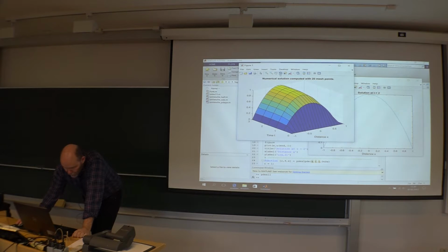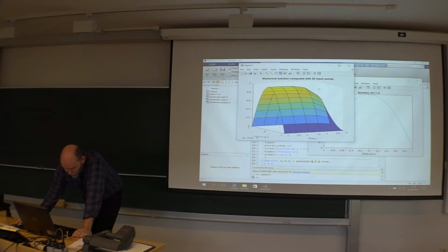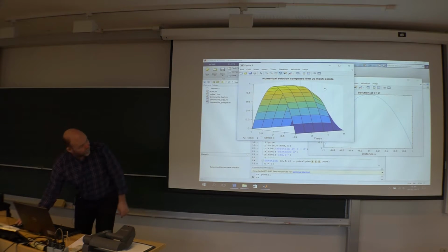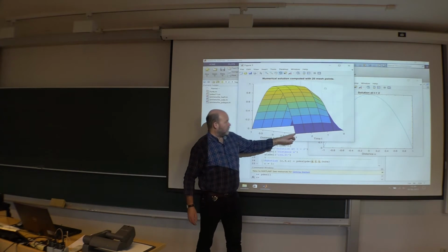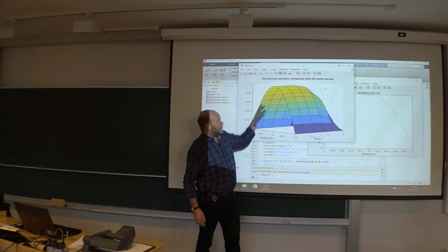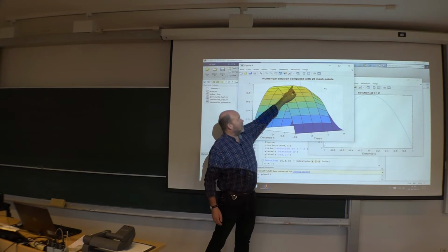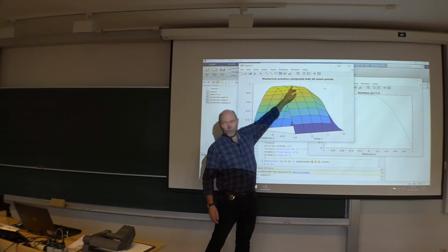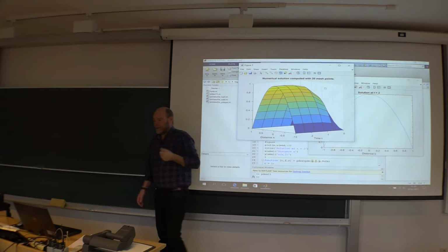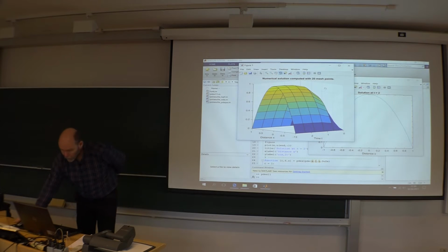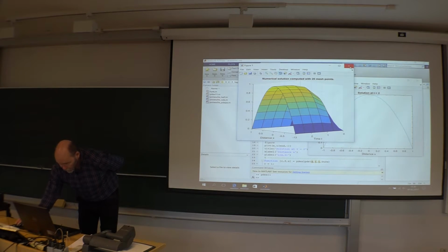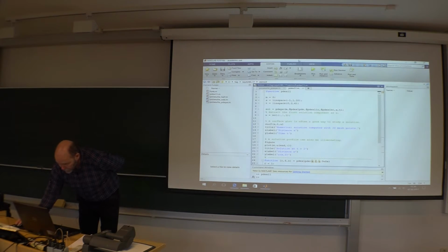If you flip this one a little bit around, you should be able to see the final steady state velocity profile quite nicely. So here time equals 3, so then you have a nice parabola, and it's fairly stable for the last time steps here. So this is a very quick way to achieve a solution for quite complex, actually, partial differential equations.